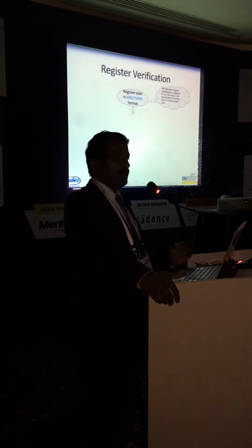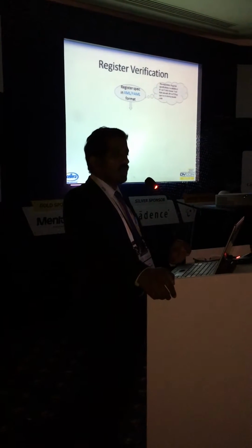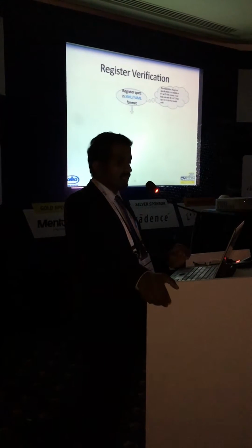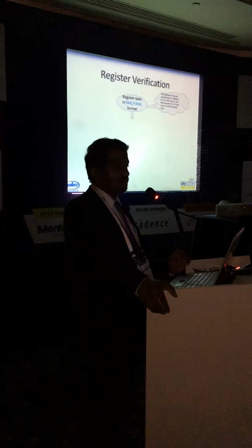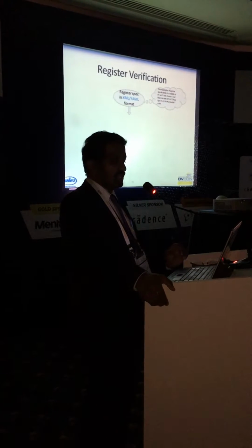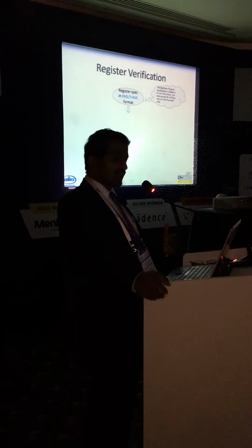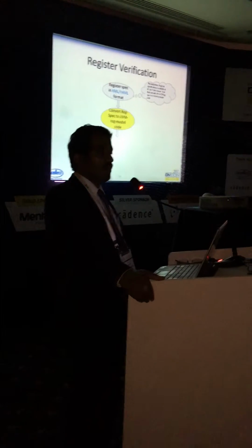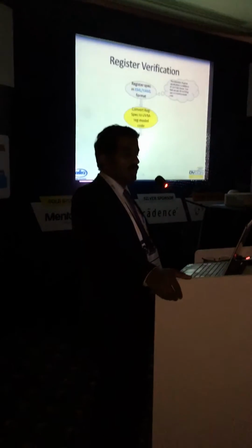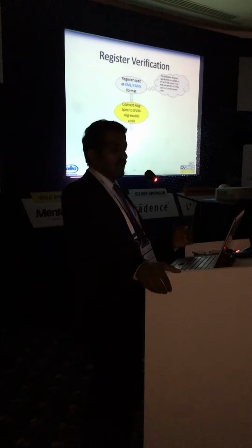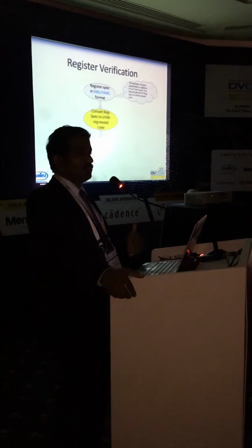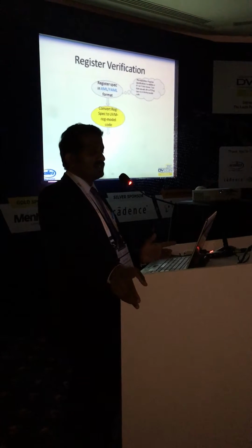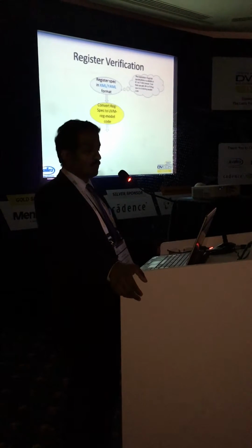So in a typical environment, the registers are available either as an IP-XACT file, like an XML, or YAML file or something like that. So most of the teams do have this even at their RTL verification stage, even at the RTL development stage, because this is kind of considered as part of your spec. What's also true is you have a bunch of generators available out there that could read in your IP-XACT file and spit out a UVM register model. This is no brainer. A lot of people have done it. There are companies living out of this. There are companies acquired due to this. Some of you probably know this.